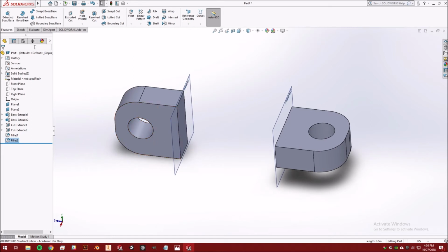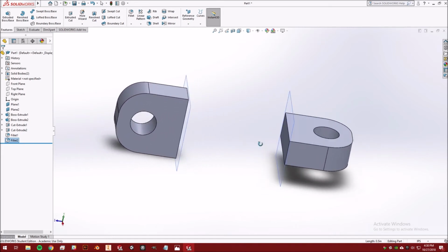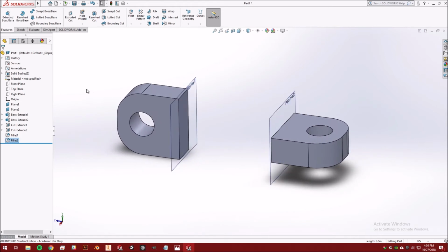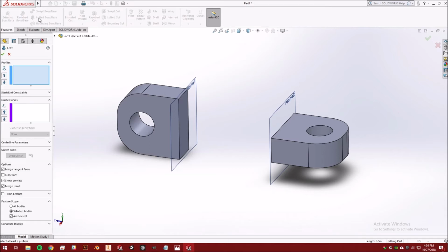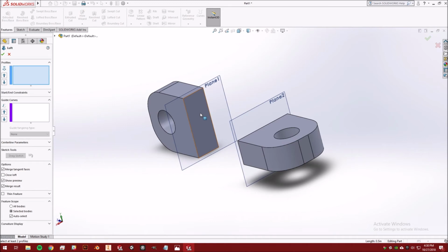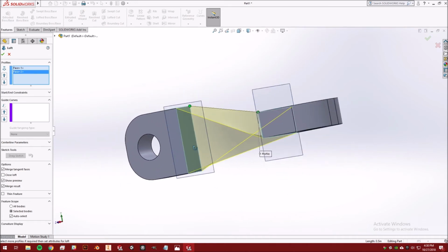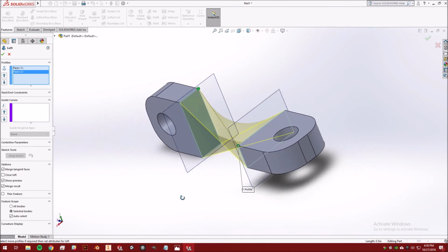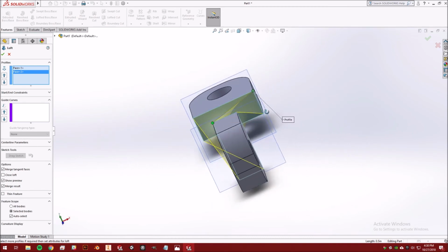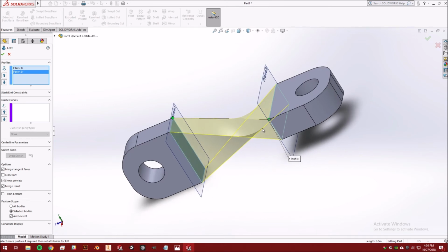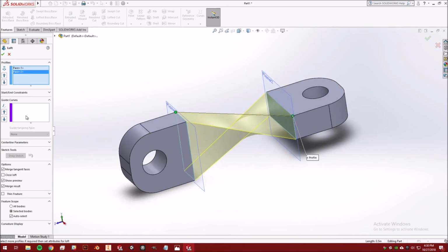Alright, so let's go ahead and go to that twisting shape here. The way you do that in SolidWorks is using the lofted boss/base tool. We'll click on this tool and it'll ask for profiles. The profiles you'll pick are this face here and the opposite face here. And you'll see that it has very simply created a curve that follows from here to here. We don't need any guiding curves. That's only if you have a more complex twist to it. This is a fairly simple twist.